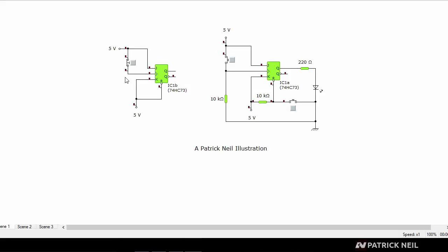However, when I break the switch it becomes low, and then when I release the switch it becomes high, then it's going to react. So take a look at it. Nothing happened, right? Because I just went from high to low. So it didn't react. So the output did not change. However, the minute I let go of the switch, because now it's currently low, the moment I let go of the switch, it's going to be high. That's when it's going to react. See that? So that's what I mean by when they react from high to low or low to high.